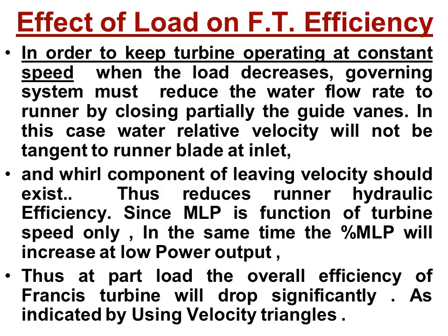Also when you reduce the load, you reduce the water power, but the mechanical loss power in kilowatt or megawatt is the same, since it depends only on the speed of the turbine. This means that the percentage mechanical loss power will increase at the same time. This means that the part load overall efficiency will drop significantly as the load drops.